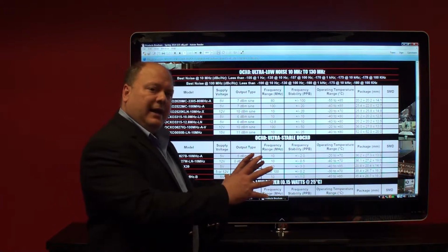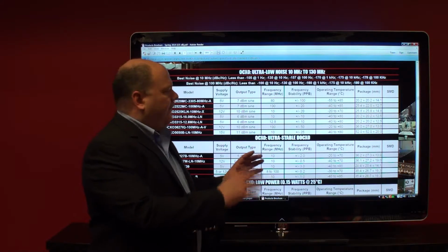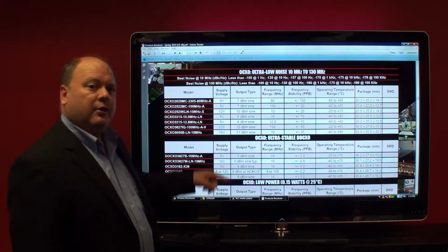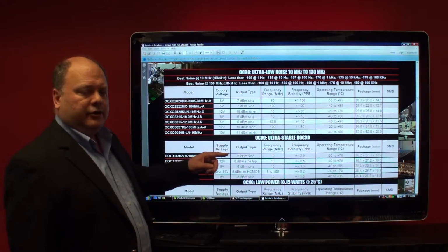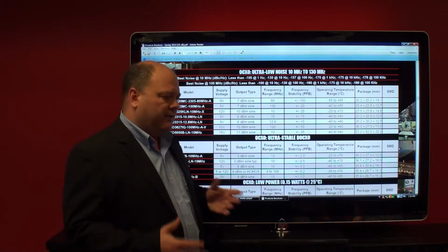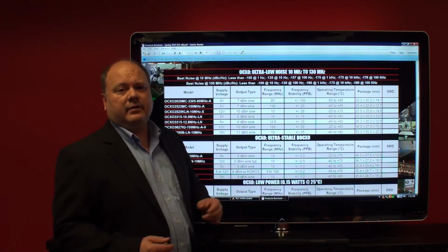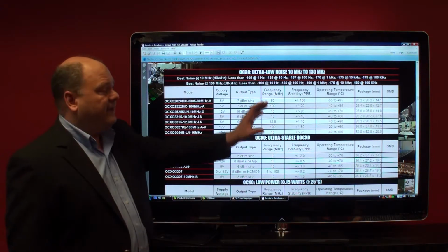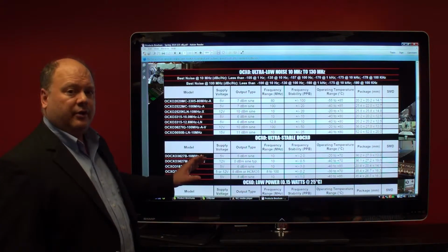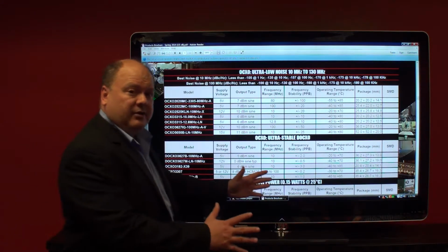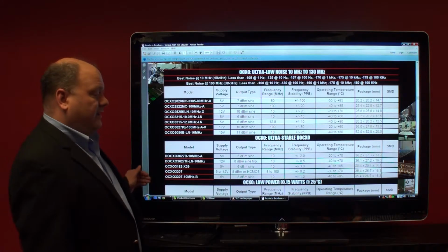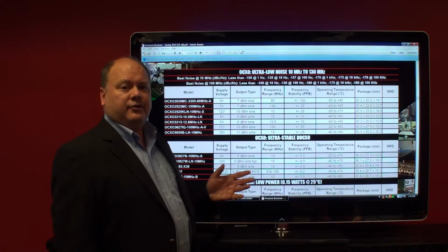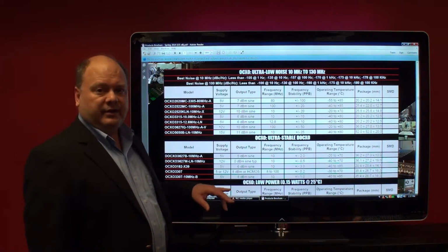The synthesizer module will have a function which phase locks the low noise OCXO to another lower frequency OCXO for the stability. So in most transceiver systems, radar systems, navigation systems, high-end communication systems, the low noise OCXO will phase lock to a more stable OCXO somewhere else, either in the box or a signal line that's coming into the box from some other part of, say, the base station infrastructure site, the building site.